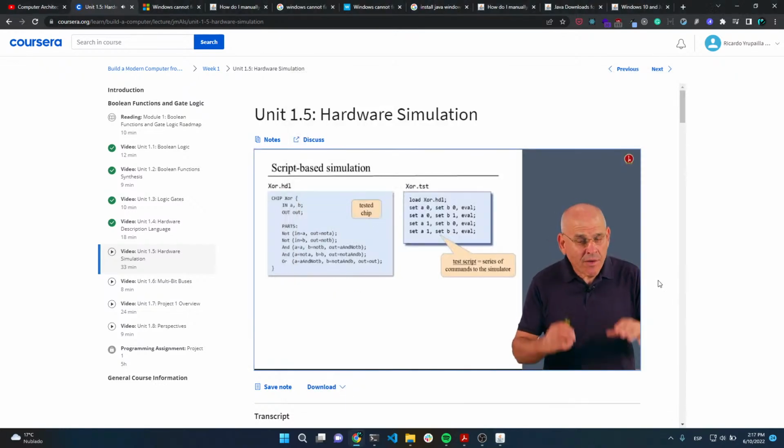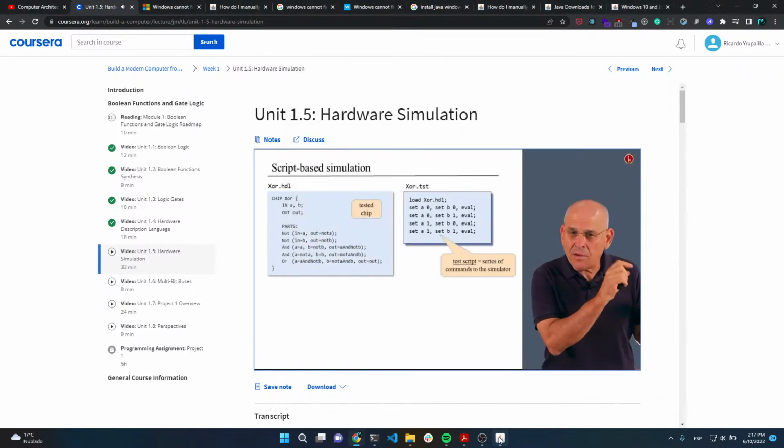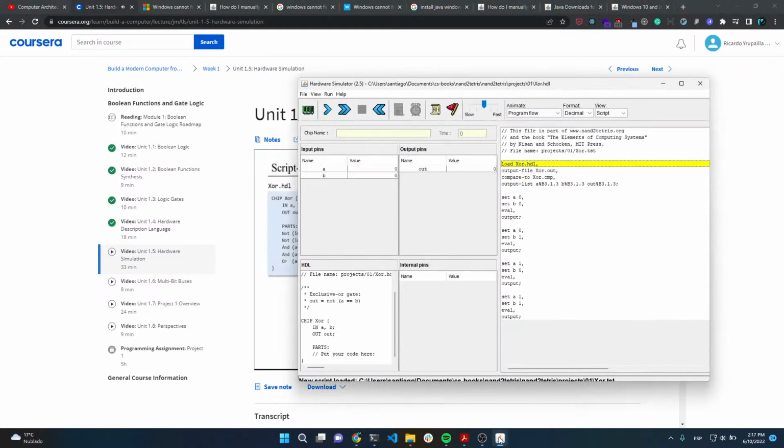into the program. So even this step is taken care of. We don't have to do it ourselves. The test script will load the program for us. By the way, this is terribly important if you do repetitive debugging, because how do you debug a gate? You use an external text editor to change the gate, and then you click save, and you go back to the simulator. So it's important to remember to reload the new version of the edited chip. So that's why we added this command to the test script.